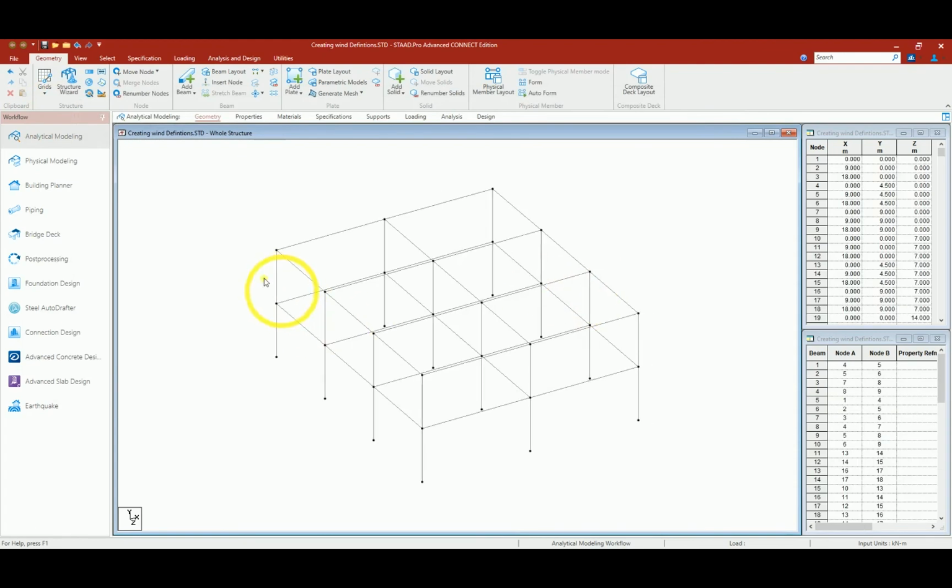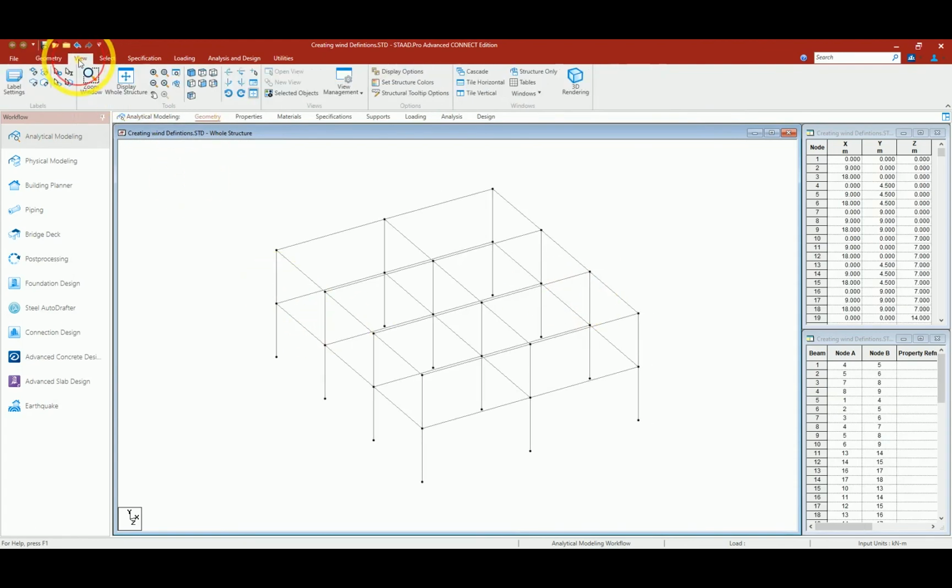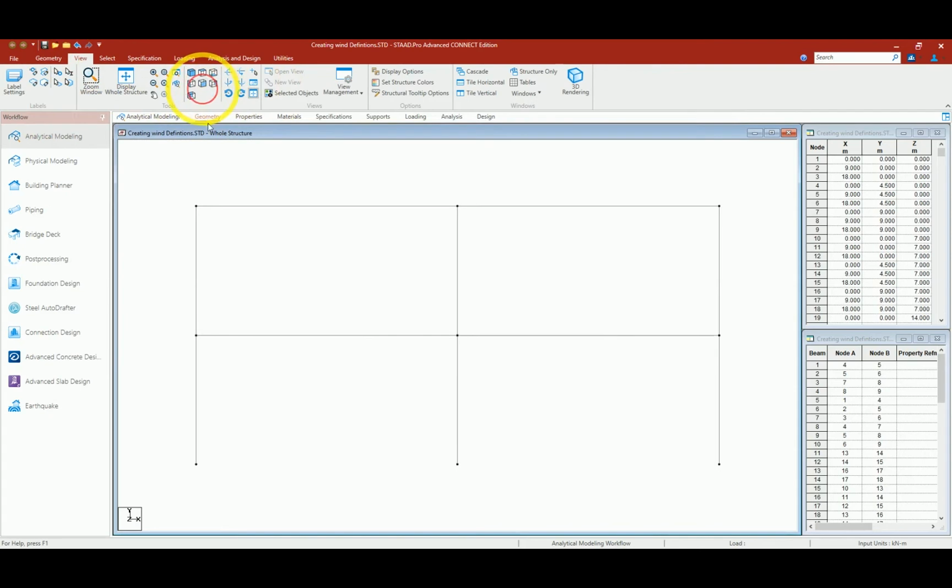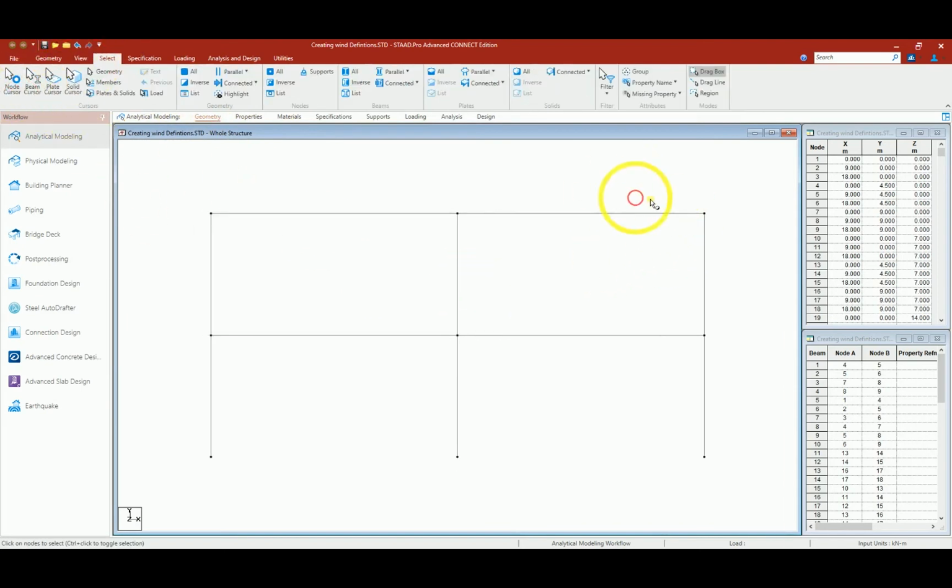And this structure I will use the variable height, that is the walls on the back side. The frame will have an additional height of 3 meter. This column is height 4.5 meter, but in back the maximum height will be of first floor 7.5 meter.